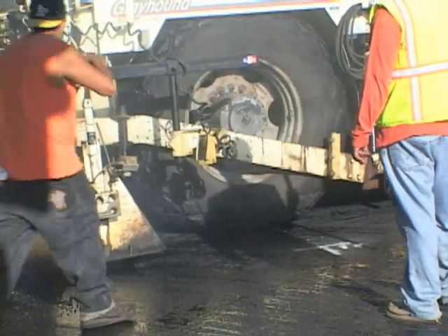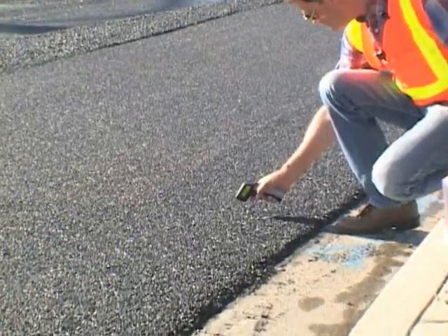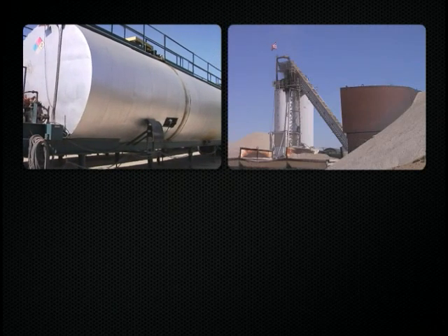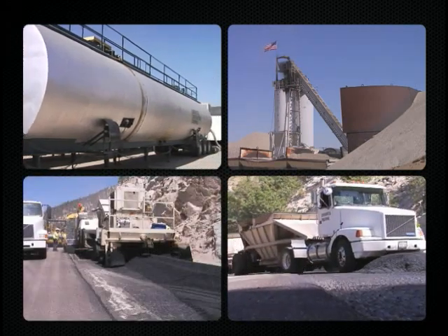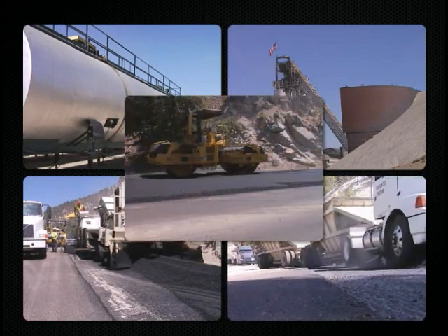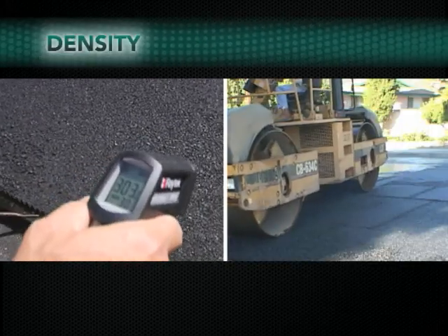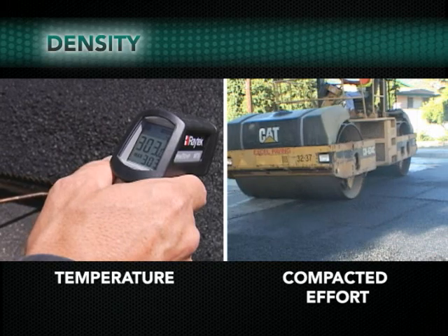Good practices for conventional HMA placement shall be adopted. Special attention should be paid to temperature management. Coordination of the binder production, mix production, mix delivery, placement of material, and compaction are essential to provide for the service design life of the pavement. In short, density is controlled by the material temperature and compacted effort.